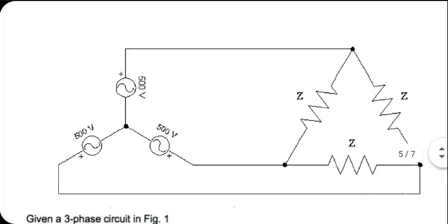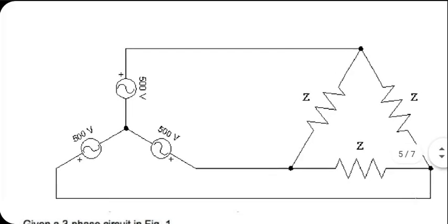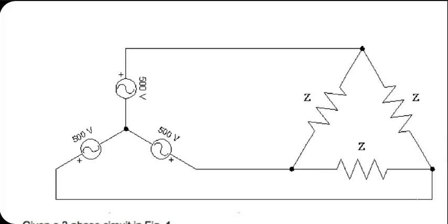So to maintain a reference zero voltage throughout the power system, it is highly advised to run a grounded wire also. Maybe it is not there in the transmission lines, but it is definitely there on the generating side as well as on the substations, where we dig a deep hole in the ground and provide solid grounding to that wire.